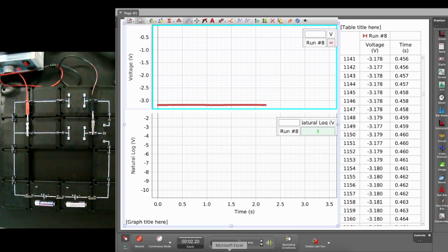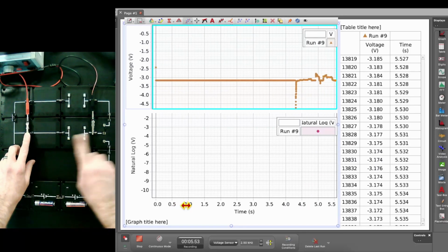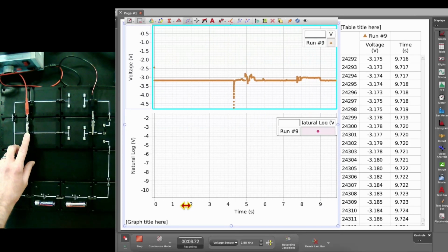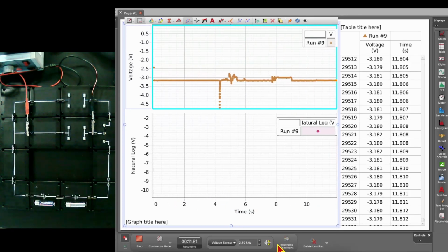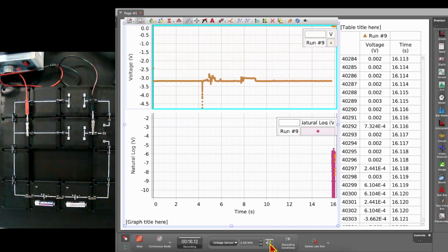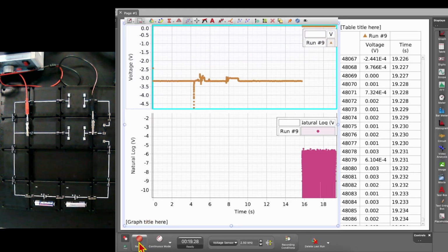Before starting anything, you can press record and notice, oh hey, the voltage sensor, which is connected to either side of where you're going to put the capacitor later, is showing a non-zero voltage right now. So like last week, make sure to zero out the sensor with the little 0 and the 2 yellow arrows right there. It zeroes it out. We're back to 0 volts. Cool, the sensor's good, and you can move on to building out your circuit.